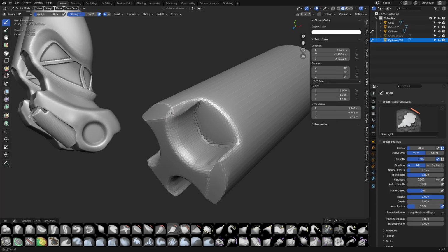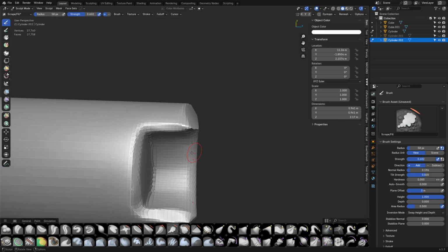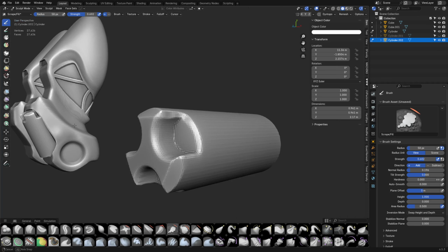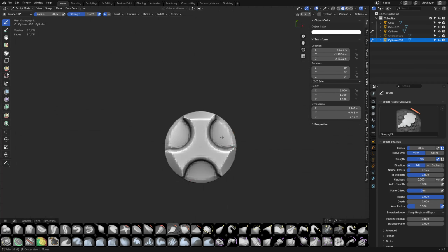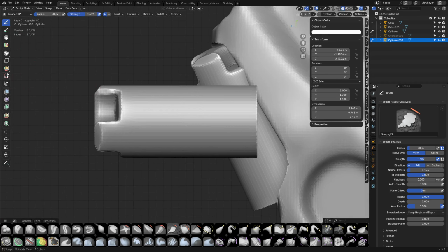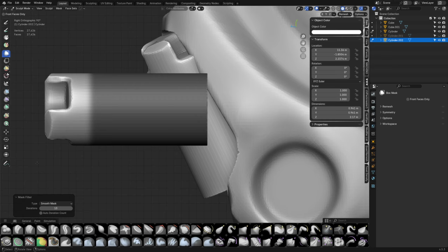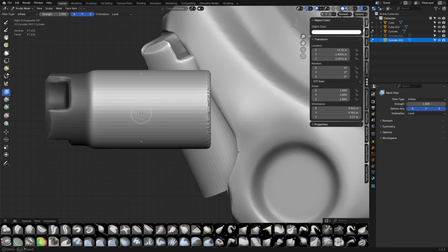So, watch some of those older ZBrush videos with pure dynamic topology sculpting, or even in Blender. You'll see guys doing this stuff. And now you'll be able to recognize it, right? That's the main thing. Being able to just go for it, playing around with shapes and forms and designs and remeshing, and then using your various tools. Like the box mask, for example, guys, how easy is that? You just box mask it, maybe mesh filter, inflate, A, invert. And you could do things like this all day, right?